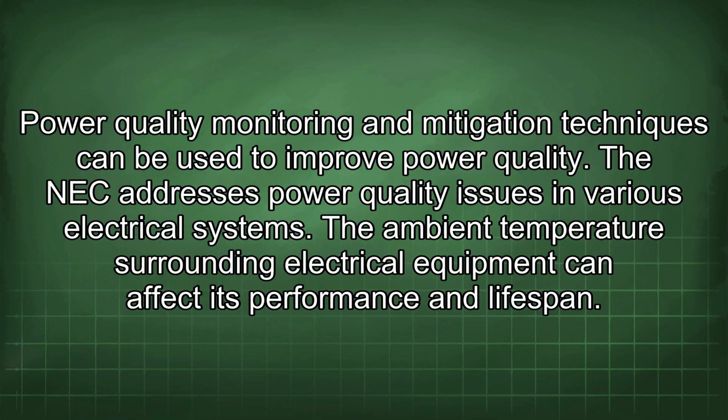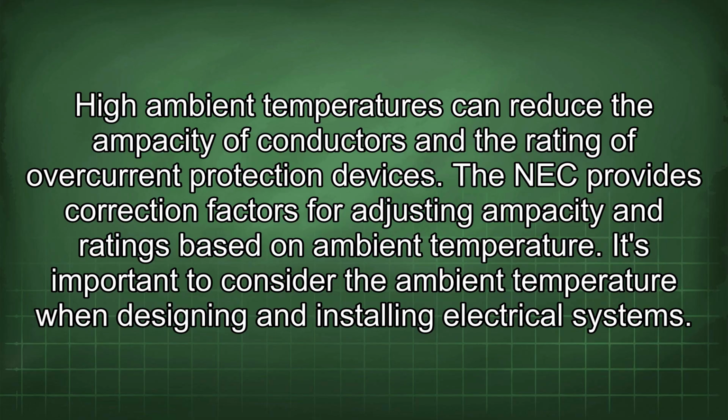The ambient temperature surrounding electrical equipment can affect its performance and lifespan. High ambient temperatures can reduce the ampacity of conductors and the rating of overcurrent protection devices. The NEC provides correction factors for adjusting ampacity and ratings based on ambient temperature. It's important to consider the ambient temperature when designing and installing electrical systems.